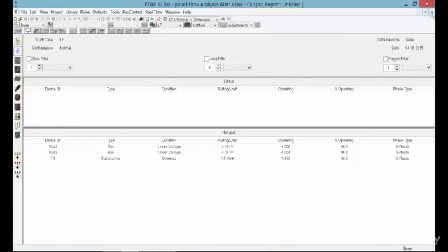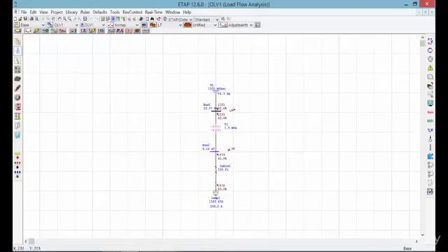So because we are operating at 96.3 of the whole capacity of the transformer, because we put 1.5 MVA for the lump load, which is exactly equal to the 1.5 MVA capacity of the transformer. So we are actually reaching that 100%, so we are marginal.